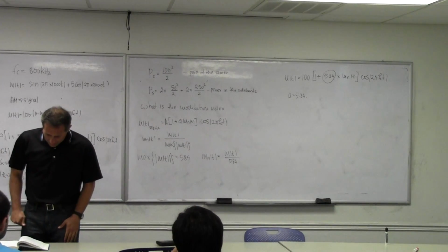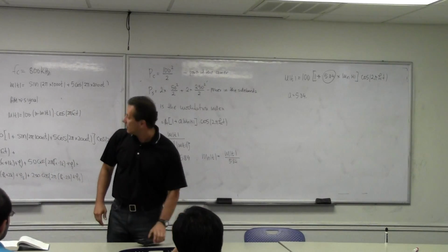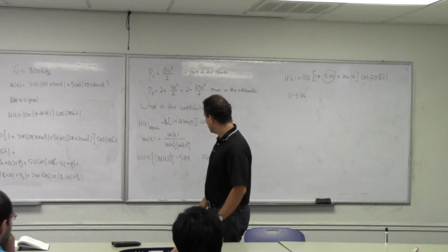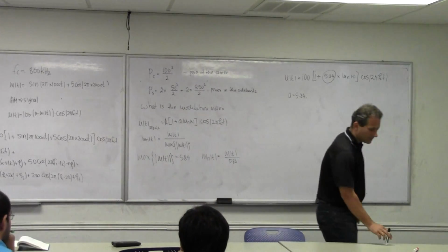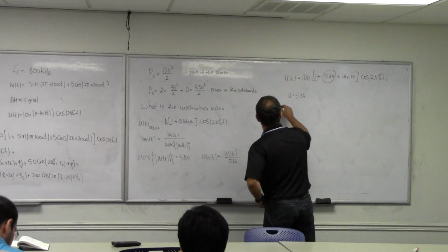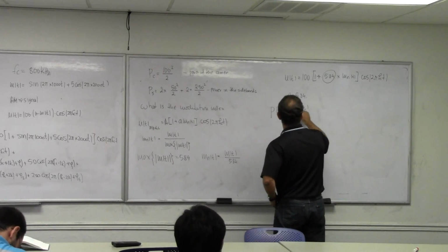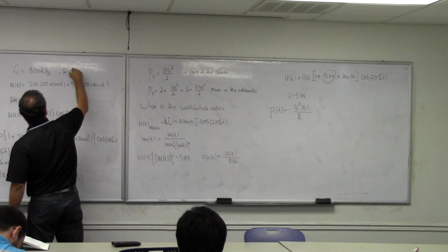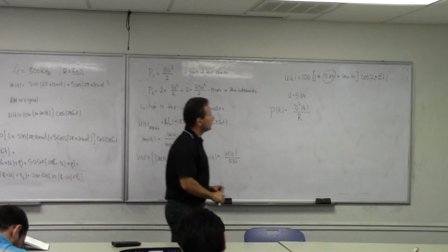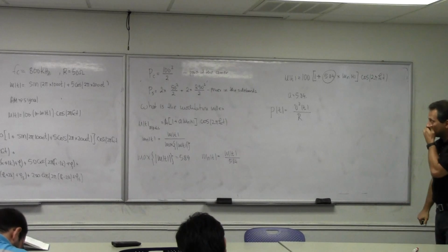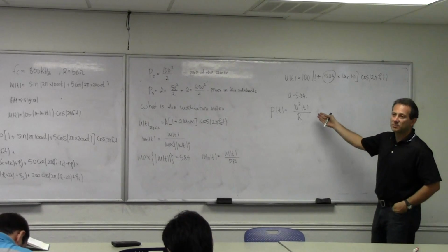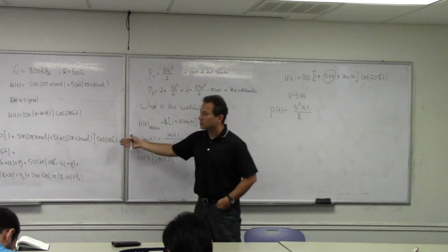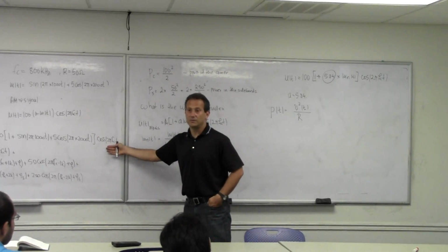And what is the peak power delivered to the load? No, be careful. What is the peak power? The power is equal to voltage squared divided by the resistance, right? Remember, the resistance for this signal was set to be 50 ohms, right? So the power here is a function of time. This is what we call instantaneous power, right? So to determine the peak power, you would have to square this whole thing and then find its maximum value on a 50 ohm resistor.